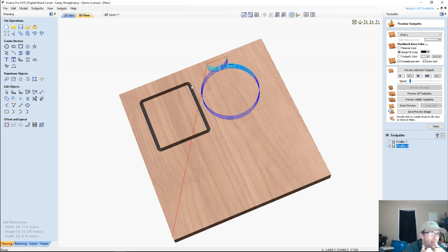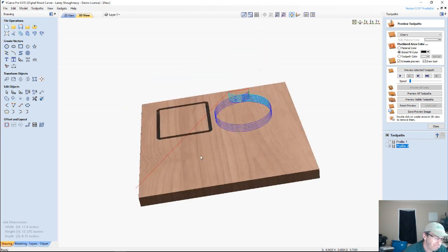That's kind of my thinking and my opinion, that it does. But here's the no side to that. What if I'm using a very cheap plywood purchased at Lowe's or Home Depot, and my bit is just grazing the top of that veneer, getting deeper and deeper, and my plywood's not the greatest? Aren't I just asking for it to start chipping up all the way around that circle, tearing out, because my bit's barely cutting into it?